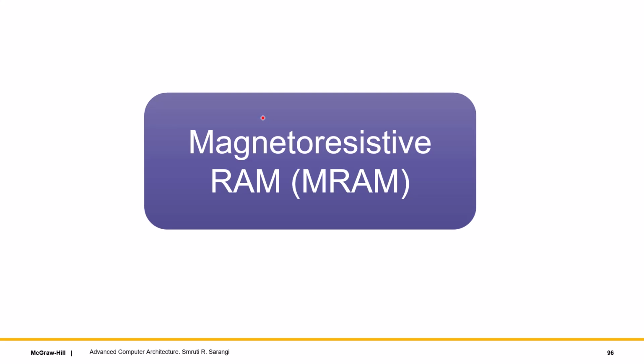Magnetoresistive RAM. This kind of memory device, thankfully, does not rely on electric charge, something that we have been seeing. It of course does rely on electric current and the direction of magnetization, which is different. And one good thing is, the moment you don't deal with electric charge, charge doesn't move, so there is less IR heat loss, less dissipation. Here we are dealing with magnetization, but changing the magnetization in general does not lead to that much of an expenditure in terms of current. We will see, but these devices have other challenges.